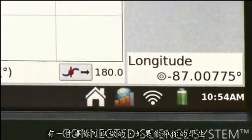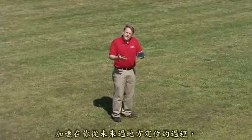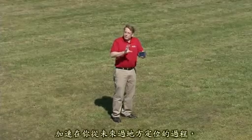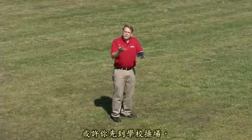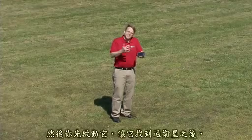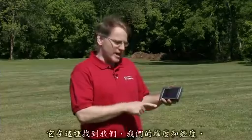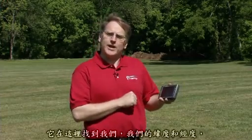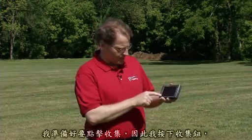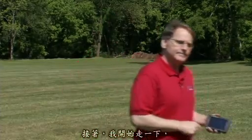One thing that you can do if you're going to use this with students out in the field, if you want to speed up the process, is that if you've ever been to that spot, maybe you're doing it around the schoolyard, you could go and activate it first and then let it find that, and then generally it will tend to find the satellites a little quicker. It's found us here, our latitude and longitude. I'm ready to hit collect, so I press the collect button, and then I go on a little walk.